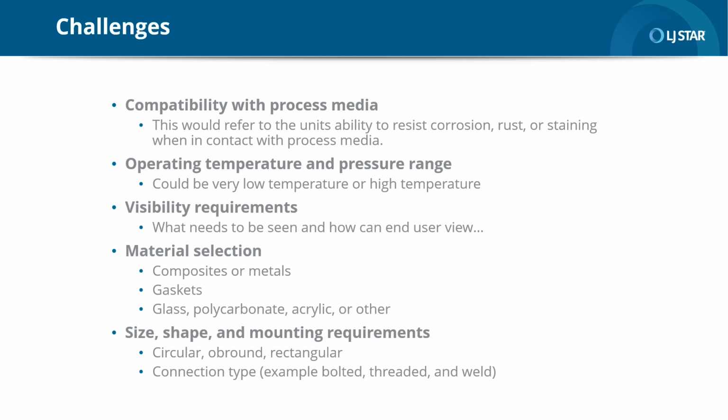What is important to you? So not only can we determine where the sight glass may best be fit, but we can also determine maybe there's a camera system, maybe there's some LED lighting that's required because it's dark inside the tank and they're trying to see further down, or they want to see close, or whatever it might be. We kind of want to get an idea of what those visibility requirements are, because it may require a circular glass, it may require an obround or a longer one down the side of the tank to determine just level. But visibility is always very, very important and can dictate a lot of the conversation when we're looking at various designs and what we can offer.